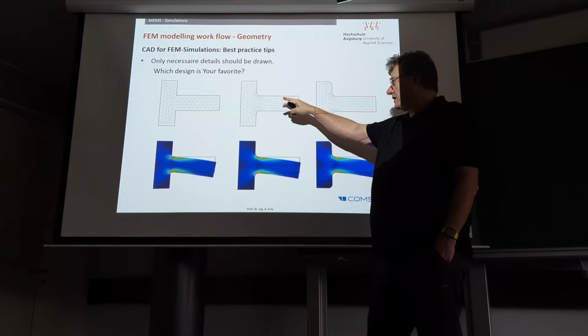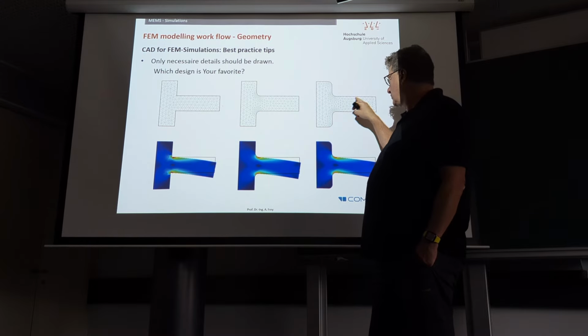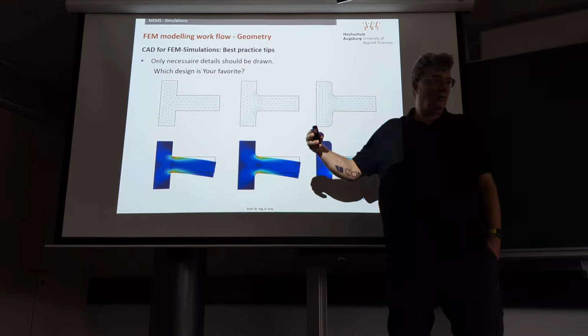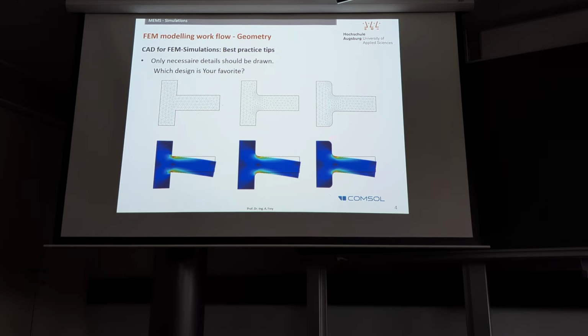In addition to that fundamental fillet, we have two more fillets. You could even put more. But this example was intended to emphasize some of the fillets which may exist in reality, but which you should skip if you simulate the part. That is definitely not the geometry you would have in real life.